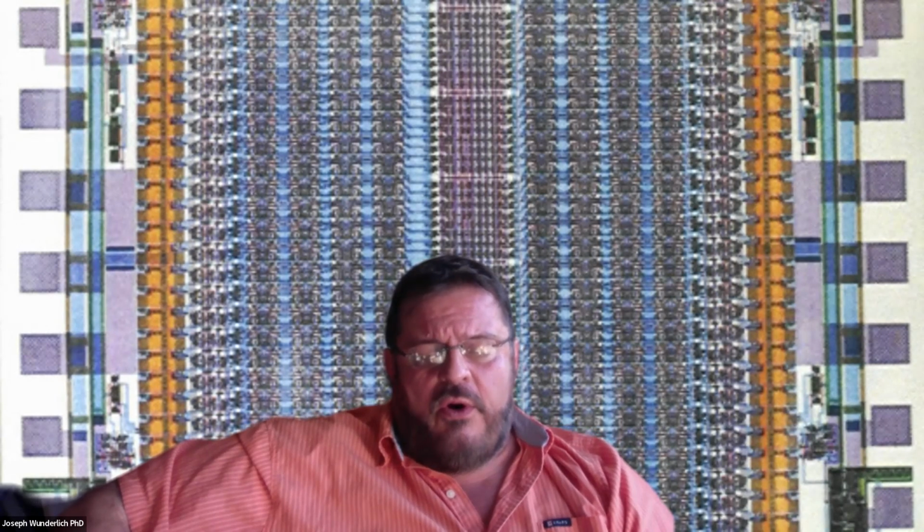And then the I/O that was mentioned in the first video as not being there really is because it's memory mapped in microprocessors and microcontrollers. So you really just need to write to a certain address. Even your 4 ports on your microcontroller, P0 through P3, they're all memory mapped. So essentially just write to them. Now there is of course some electronics you need to work out with pull-ups and things to make the signals work and make sure you're not reading from the buffer instead of a pin. There's a number of little things.